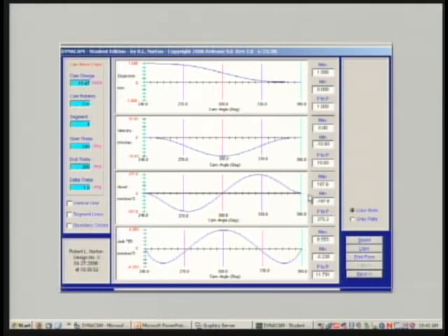If the slope is 0, then it starts off with that 0 slope, let's come in from the front end, and then climbs up to a higher value of peak acceleration than I would have had in the 3, 4, 5. By the same token, tying this jerk to 0 at the beginning further flattens the velocity. The flattening increases with each integration. Notice how flat it is at the beginning of the displacement.